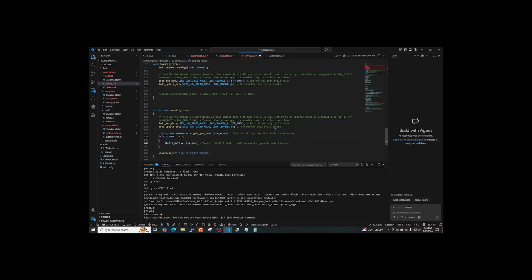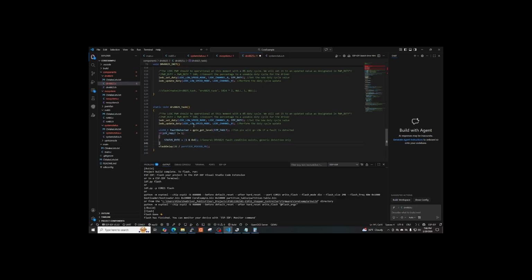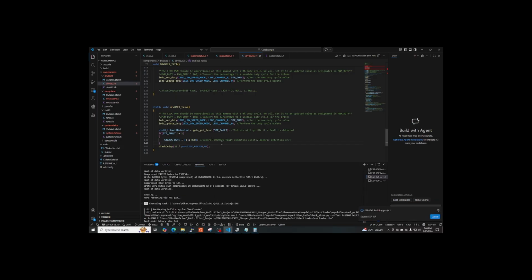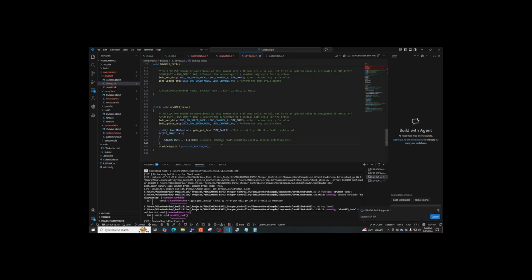All right. Because it's going to be doing this, we definitely want a little delay in here, 25 milliseconds. Again, we don't want to run into the same situation where these tasks are just stealing from the main CPU tasks and doing what it did before.